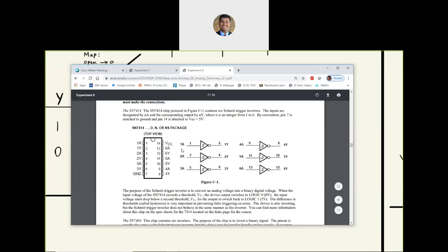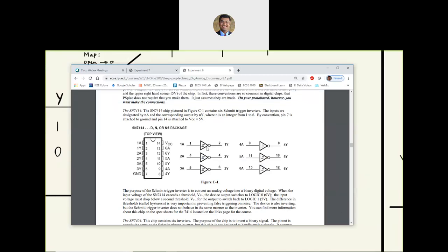They are all performing the same operation. Input is a low, output is a high, input is a high, output is a low. But this NOT gate is based on Schmitt trigger, meaning two thresholds. So there is some tolerance to noise, but it could also be a comparator based inverter where there's no tolerance to noise and there's only one threshold level.